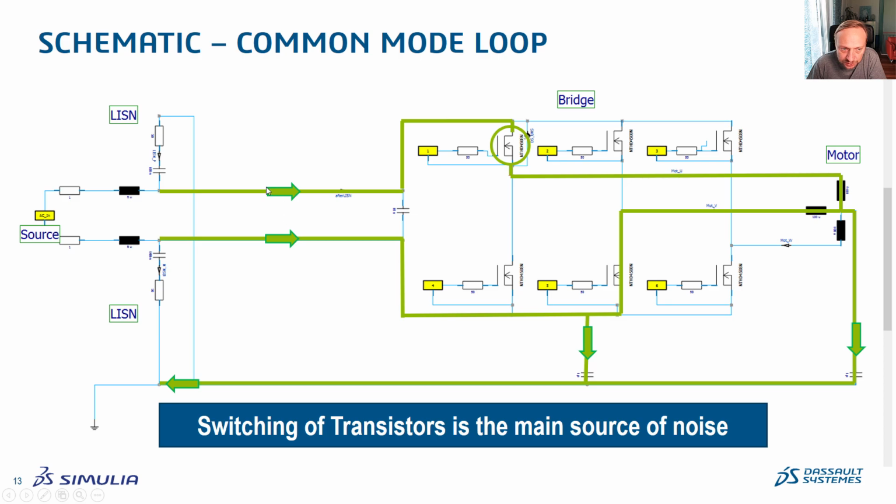And you see it's drawn here. So these two arrows now point in the same direction, while this one points in the other one. So we have basically a voltage between this arm and the PE arm. And looking at this, there is a very general rule: at the low frequencies of the switching, the differential mode will typically be higher than the common mode, while at high frequencies, the common mode is typically higher than the differential mode. It's a rule of thumb, of course, because these capacitors have a high impedance at lower frequencies, while at higher frequencies this impedance decreases and more of the common mode emission will be present. And we will look into this now in detail.